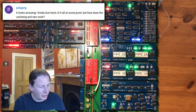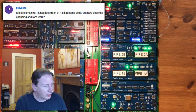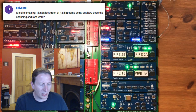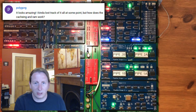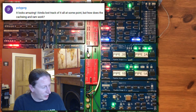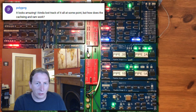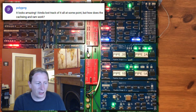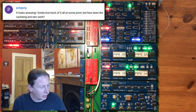Anything more complex than that was kind of unnecessary, but particularly if I wanted to break that relationship, where every single memory operation suddenly becomes a 2-cycle op because I can't fetch while that instruction is executing, then having some caching or some separation like the Harvard architecture would have been interesting. But I really didn't want to go down that road, because straight Harvard architecture introduces restrictions on the processor, because suddenly you can't treat code memory and working memory as the same thing.